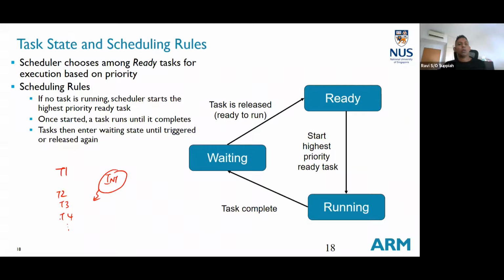execution flow so that instead of task 1 that is running, I should preempt task 1 and make task 3 take over. Task 3 takes over and task 1 comes in and waits, because task 3 is now more important because this event has happened. So now the tasks have this new parameter associated with them known as the state of the task.